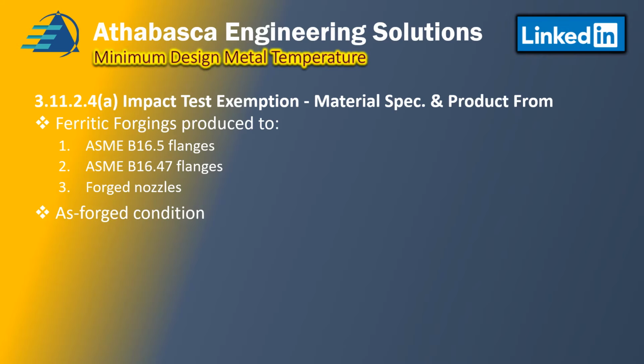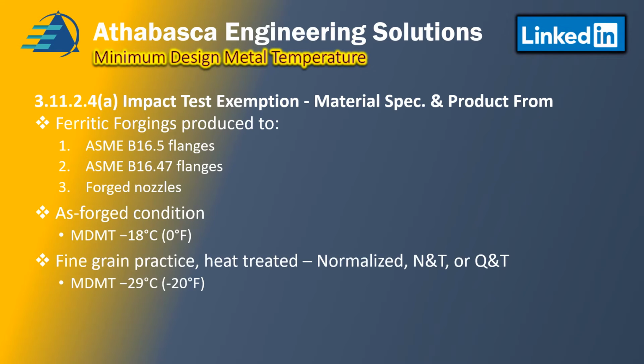For an as-forged condition, which means it hasn't undergone any subsequent heat treating, it's just been forged and then slowly cooled, you automatically get your MDMT down to minus 18 degrees centigrade or 0 Fahrenheit. That's the basic exemption.